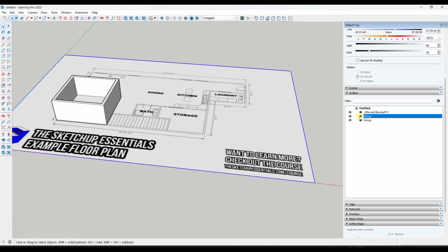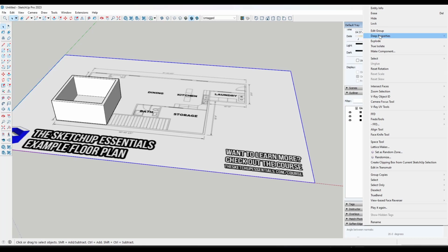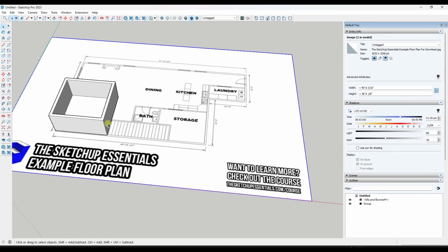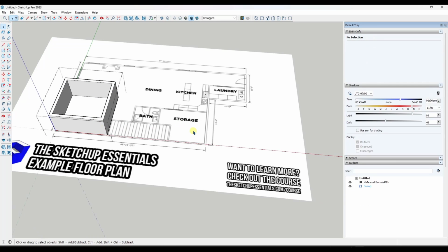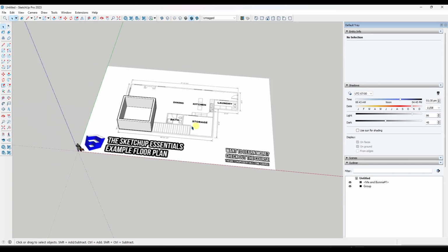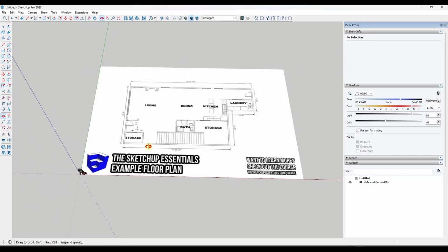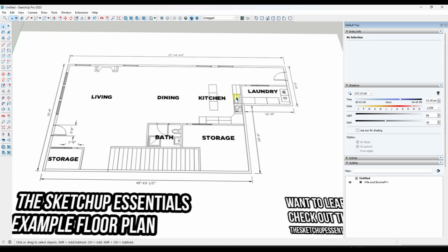So when you delete that group out, like this, then you just have an image file in here. Well, now if I double click on this object, notice how it doesn't fade. So that's just kind of a weird deal. I wish you could turn off the texture fading when you're editing groups and components, but you can't. So that's how we're going to fix that.